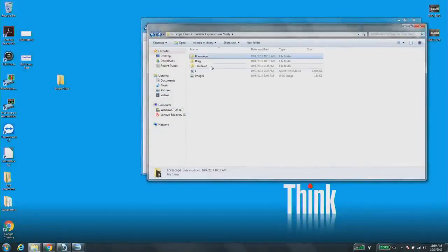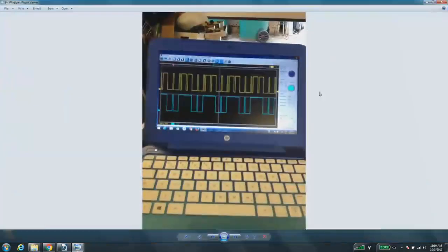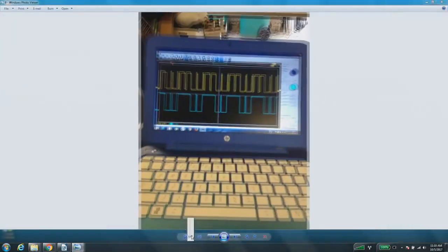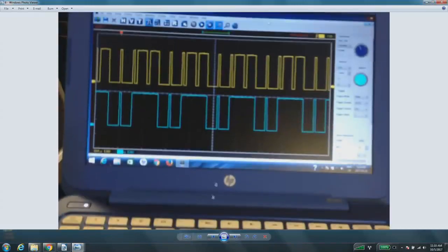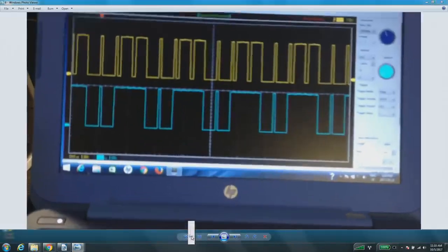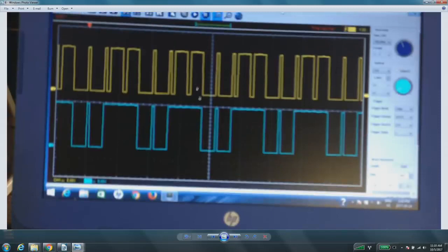All right, so when we're looking at our diagram here, what we're actually seeing is our missing short triggers, okay? So even though we have these trigger points on here, these longs and shorts, it's the opposite of what you would think when you're looking at the scope. You're thinking short would be those 2 short triggers, but it's just the opposite. It's when it goes down to 0 volts that's when that metal is passing by our sensor, okay? So when that metal isn't passing by, our sensor stays high voltage here.